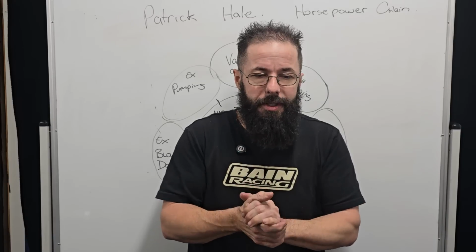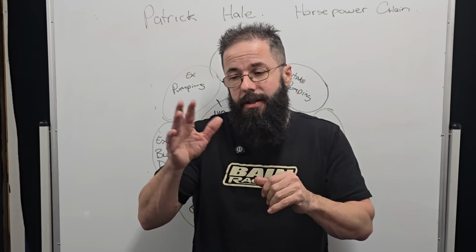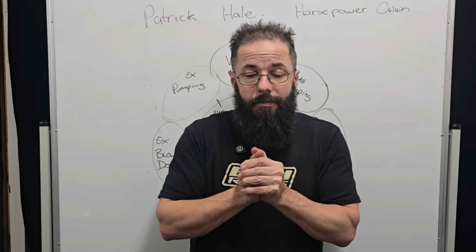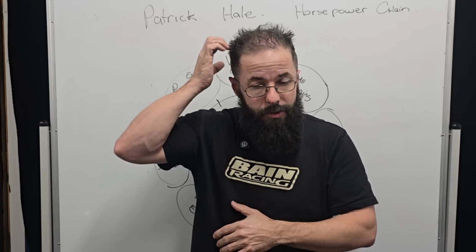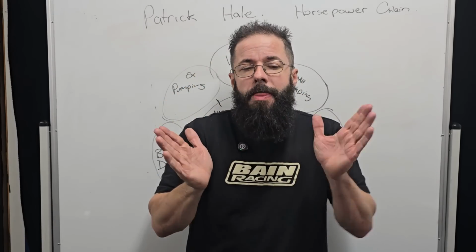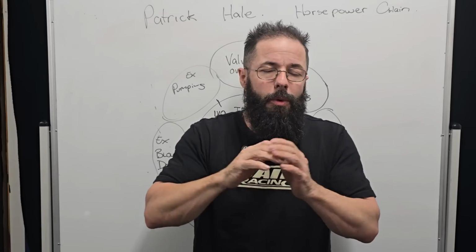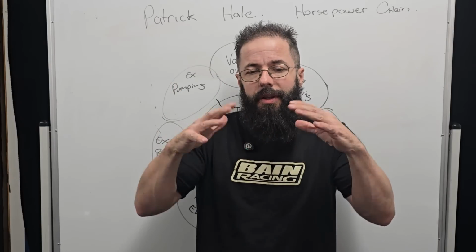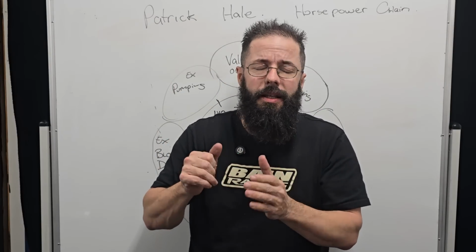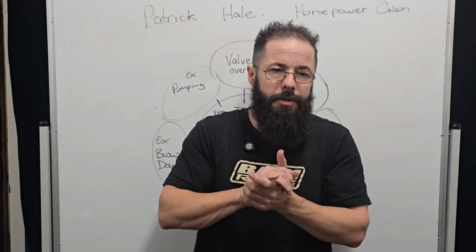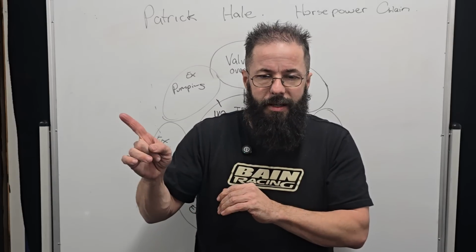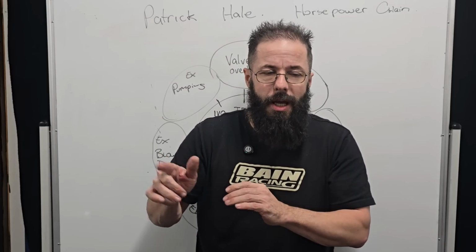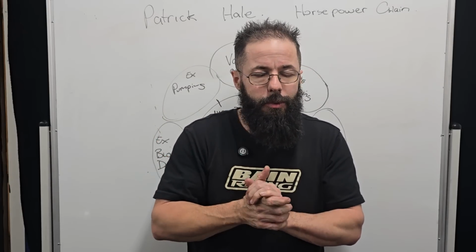And again, this is what we've seen with our 1 and 2Js and our RB camshafts. And I think it was turning point that I was getting into. Just playing with the LSA, we were able to move the power curve over 1,000 RPM and just fill this curve out. And again, I think it ended up making about 1,000 horsepower at 30 PSI on one of our customers' 2Js, but he was tuning that.